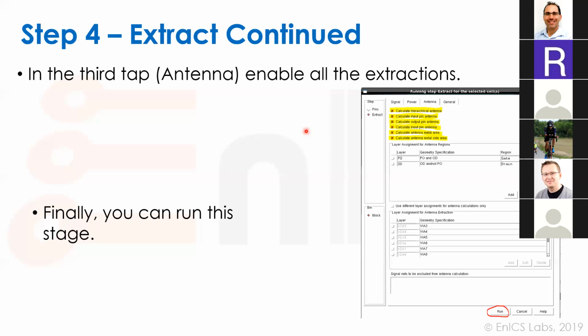That's it. I will even add to that with the power grid, if possible. If you're not doing just a general thing that will be used somewhere, but you're using it on a specific chip, you should always generate the power grid according to how the top level plans to connect to it. And if possible, in some cases, you could even make your power routes at the same intervals and pitches as the top level, and it could even seamlessly connect to them. Yes, exactly. Like sometimes we integrate it.